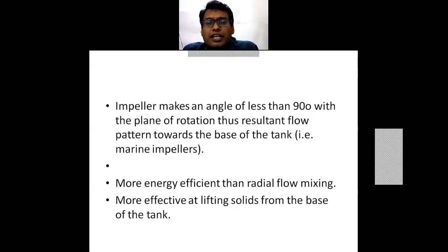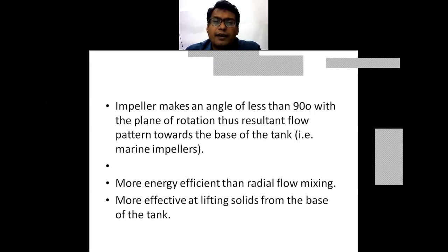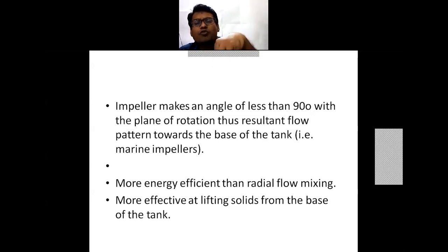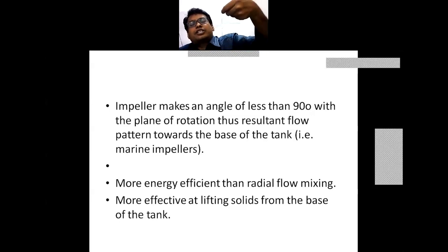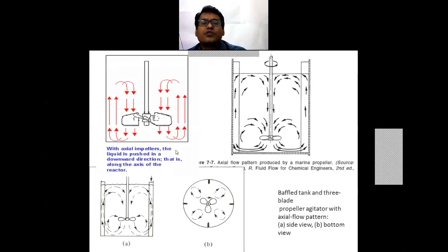It is more energy efficient because the fluid will not directly impact the blades; it will move at a certain angle. It is also more effective at lifting solids from the base of the tank. As you force the fluid to move in the downward direction, the bottommost solid material is lifted in the upward direction, and it develops a circulation loop.